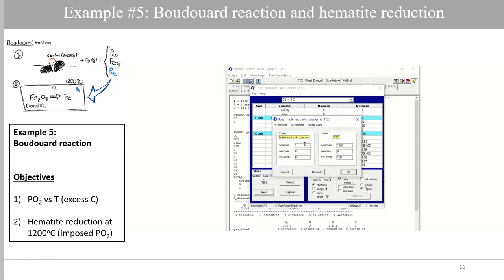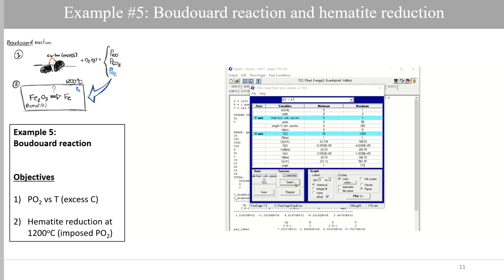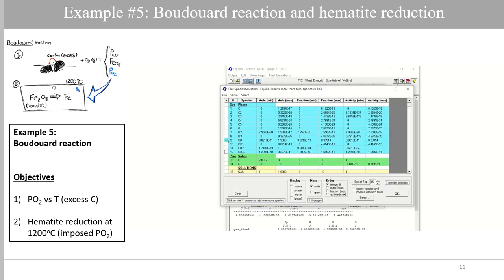Like I've mentioned previously, we go up to a value of about 7.55 × 10^-18. So what I'll do now, I'm going to add a maximum value of 10^-17, and I'm going to tick every 1e-18. So now I'll be able to see the behavior of the partial pressure of oxygen as a function of temperature in my system. Next is to select specifically my O2 chemical species in the gas phase.